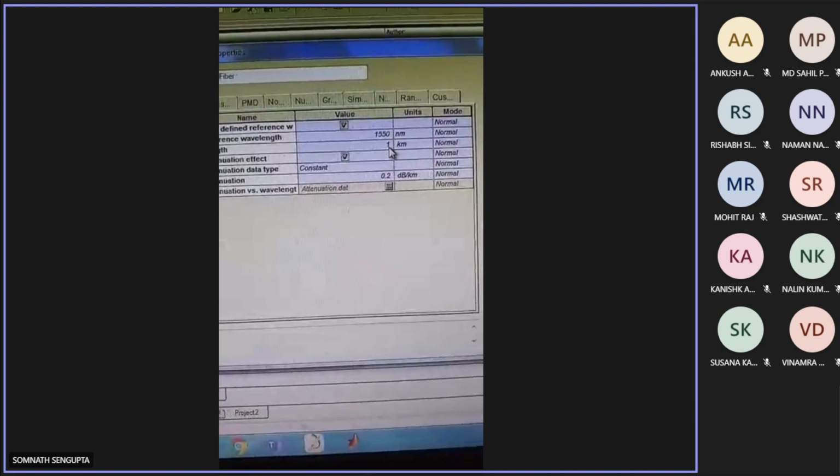After that, we see the detected light. It is in analog form, so you have to convert it into digital form. For that, you have to use a threshold detector. Either a multi-level or single level detection is sufficient. Then you have to apply it to the D flip-flop. So now let us see the waveform.